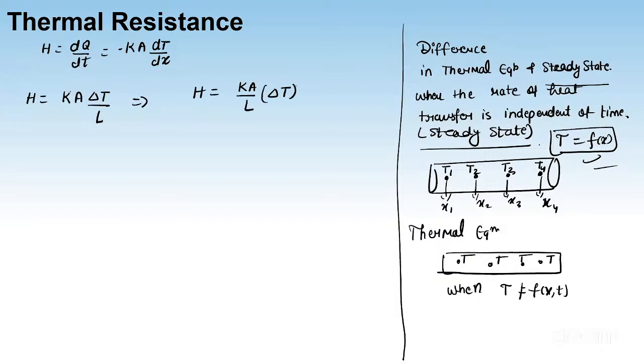अब देखो ये delta T क्या है, this delta T is the driving force, isn't it? The driving force. Due to this change in temperature, this heat transfer is taking place. ठीक है, so this is the driving factor or the driving force. ठीक है, this is the rate of heat transfer, which means dQ by dt. So if you compare it with Ohm's law, for now you can relate it.